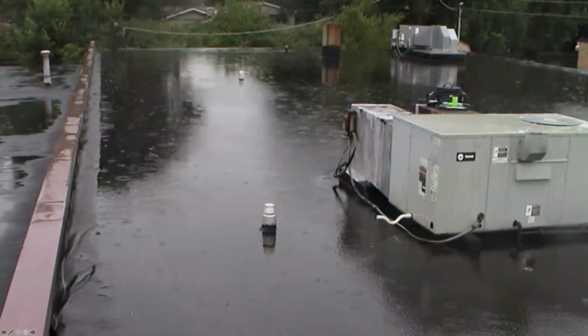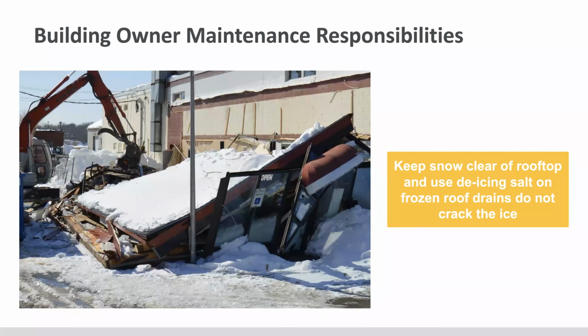And can you imagine if the drains were clogged there and you have a new rooftop swimming pool that you didn't expect? And if one of these details here does fail, or maybe a puncture, something there allows these hundreds of gallons of water to come down. We have a tremendous catastrophic issue inside your building. And imagine if it doesn't get off and it freezes and you have a live load of snow and ice. Now, I don't think that's what happened to this building, but it's just kind of a cool picture. I recommend keeping those waterways, again, I can't stress enough, clear and free so that water can get off your roof.